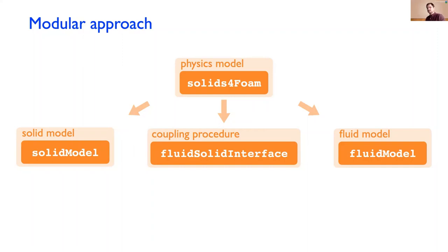If you want to do that, the traditional OpenFOAM approach would be to make a new solver called something like pimpleSolidDisplacementFsiFoam. And there are solvers like that. I know I shared one called icoFsiNonLinearElastic something, or there was fsiFoam in a few different versions. They have a hard-coded version of the fluid solver and a hard-coded version of a solid mechanics solver. So if I want to make a new solver using a compressible fluid formulation, I actually have to copy a lot of code and make an entirely different solver.